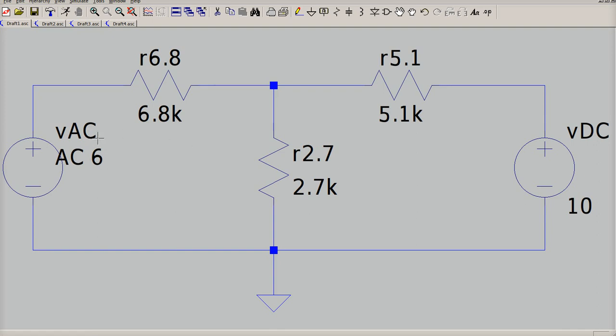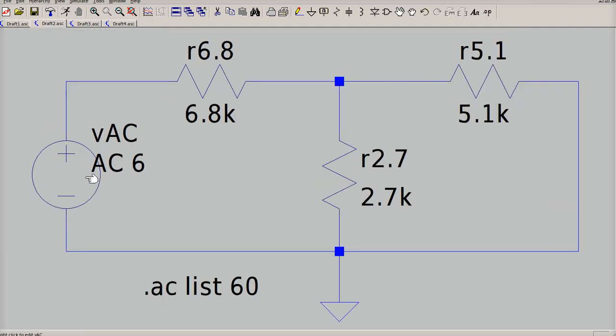So if it's a voltage source and you want to remove it for some kind of analysis, you would short it. If it's a current source, you would leave it open, or you would leave it out of the circuit. So this circuit becomes two circuits. The first one is the AC side, and this is the same circuit that you saw on the last page. I redrew it, same values, everything's the same except there is no DC source here. Now that I have a one voltage source circuit, I can in fact solve it.